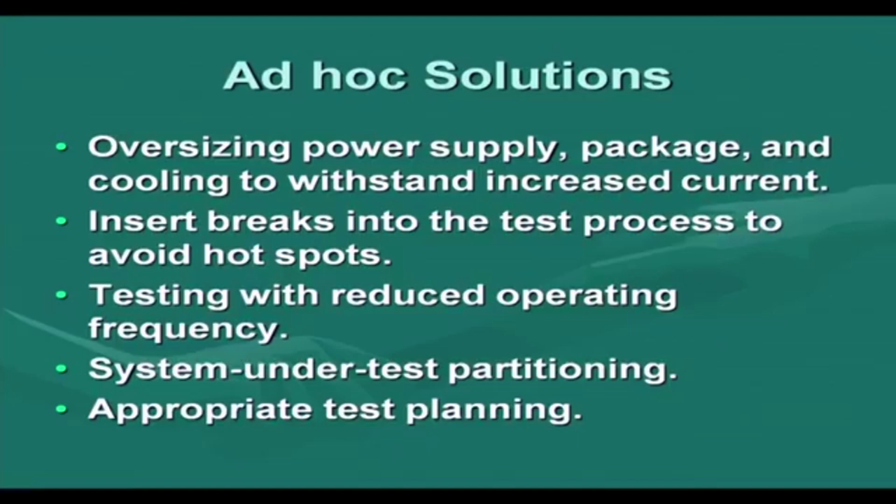Maybe if a total of 1000 patterns are to be applied, we apply 100 patterns, take a break, then again apply 100 patterns, take some break. That will allow the system to cool down. When it cools down, the static power consumption or leakage power consumption will come down. As a result, the test power can be reduced.